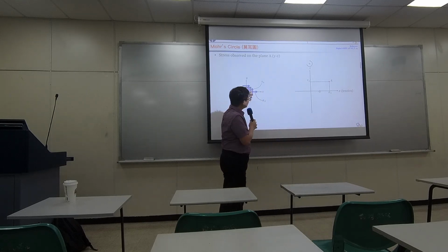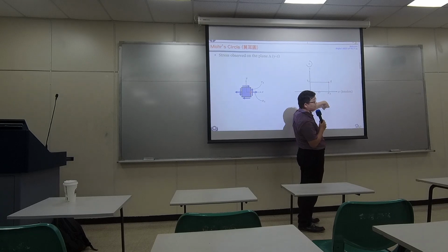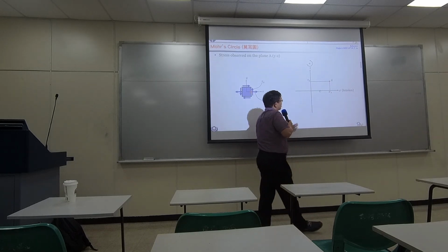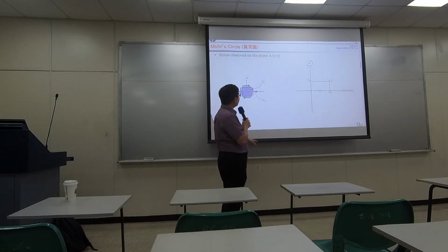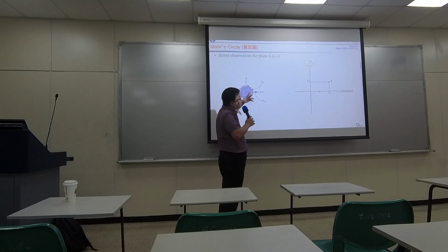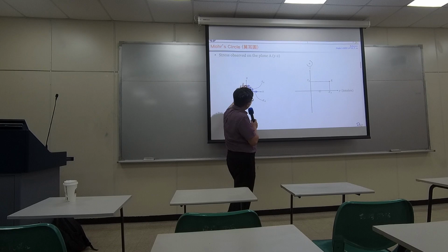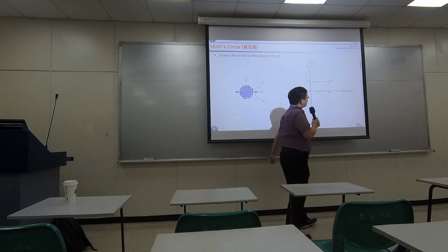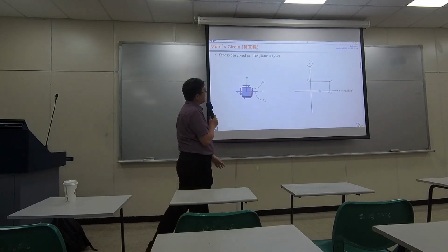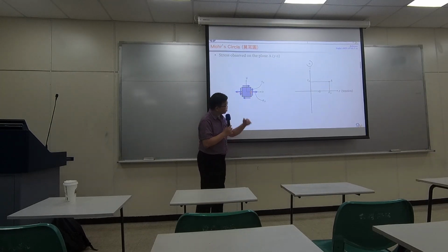So if you choose clockwise as positive, then the point will be at the bottom, right? Either way. Now I say counterclockwise positive, so I know from my analysis, I realize there is a counterclockwise shearing stress in the magnitude of tau A, so maybe some value like this right here. So I pick a point, I specify a point. So that's the loading condition at this particular direction.